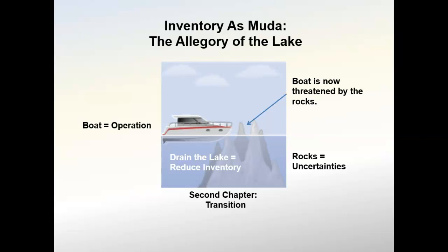While the traditional view of the second image in figure 12.8 is one of danger and crisis, lean philosophy considers the second image as a positive situation. At the beginning, the problems and uncertainties plaguing the system were hidden by the inventory levels. But now they are being exposed by carefully dropping those levels, with the most significant problems emerging first.